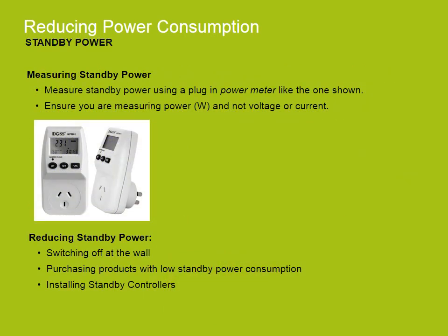You can measure the power usage of an appliance using a plug-in power meter. Plug-in power meters are a useful tool for an assessor to carry as they allow you to spot measure appliance energy use while auditing. As an initiative, they are also good for making clients aware of their energy use by displaying in real time the consumption of particular appliances.